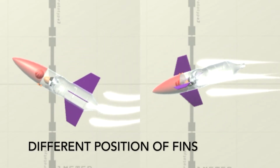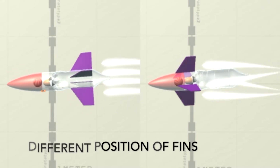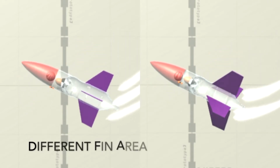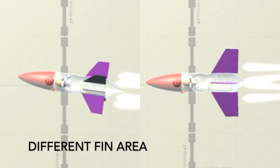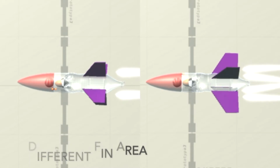Placing the fins at the bottom of the rocket increases stability by moving the center of pressure further after the center of gravity, providing a greater restoring moment, allowing the nose cone to realign with the velocity vector. Increasing the fin area also increases directional stability, as it causes the center of pressure to also move further after the center of gravity. However, by increasing the fin area over a certain point, the restoring moment will become too large, making the rocket directionally unstable.